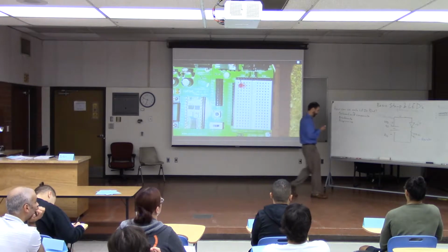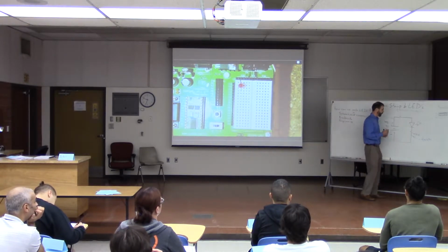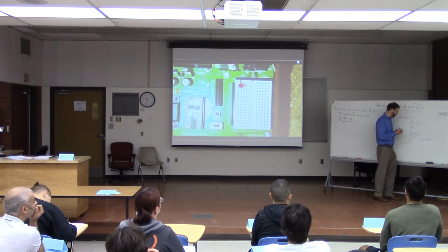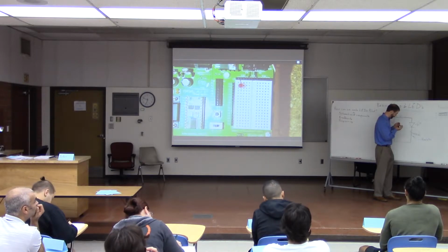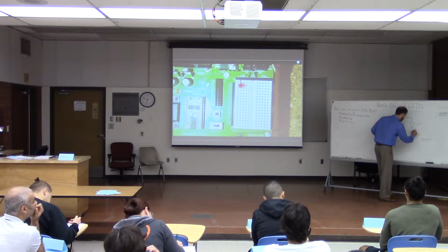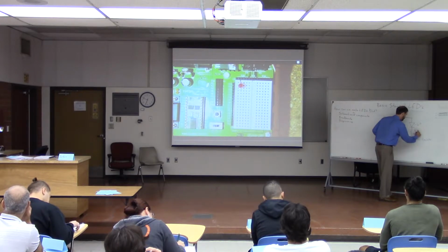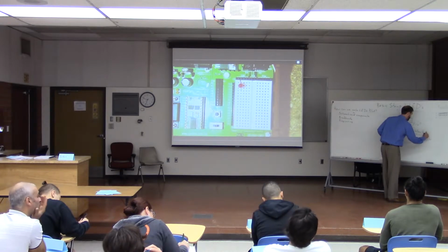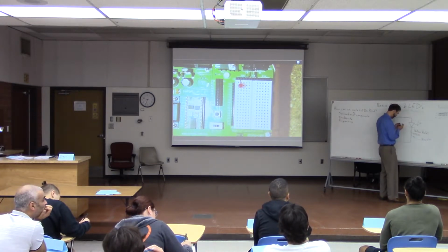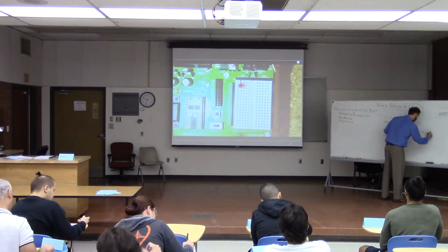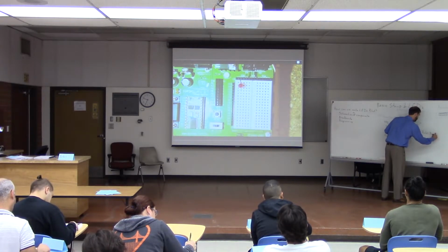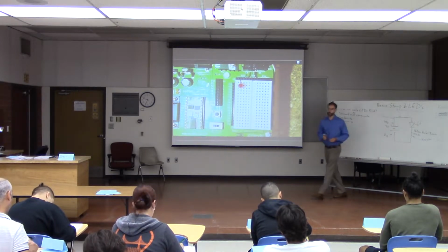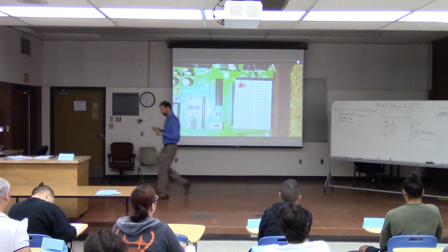We're not going to go into what all the colors mean right now, but we do need to know what a 470 ohm resistor looks like. So that one is yellow, violet, and then brown. Okay, so we're looking for a resistor that has color bands on there that are yellow, violet, and brown.